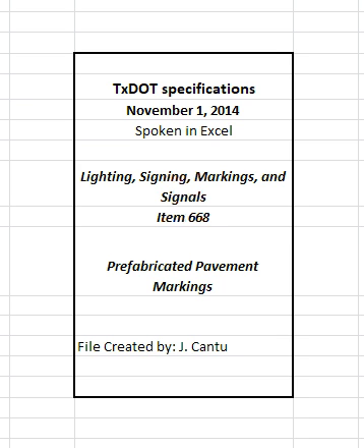3. Construction. 3.1 General. Obtain approval for the sequence of work and estimated daily production. Remove all waste generated from the job site before the end of each working day. Establish guides to mark the lateral location of pavement markings as shown on the plans or as directed, and have guide locations verified. Use guide material that will not leave a permanent mark on the roadway.